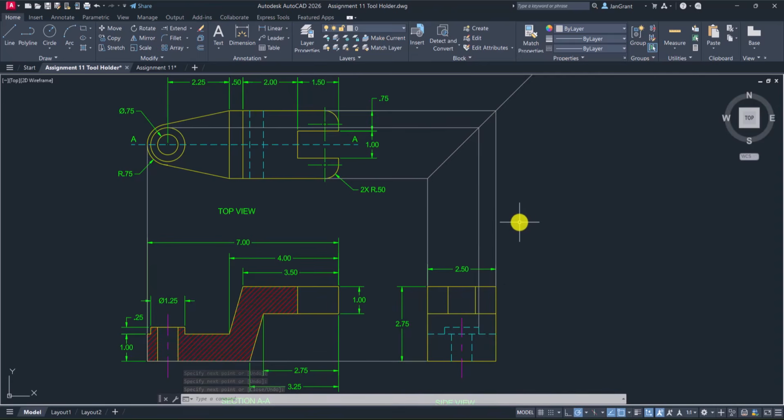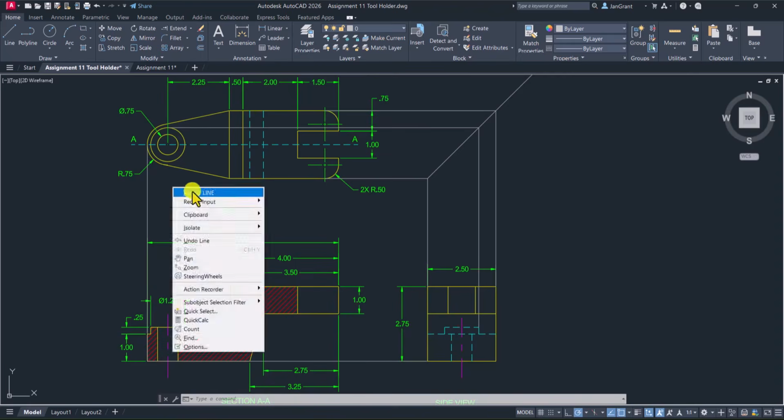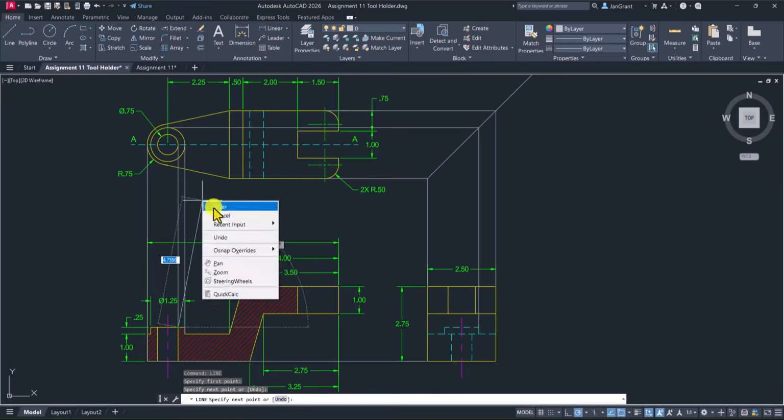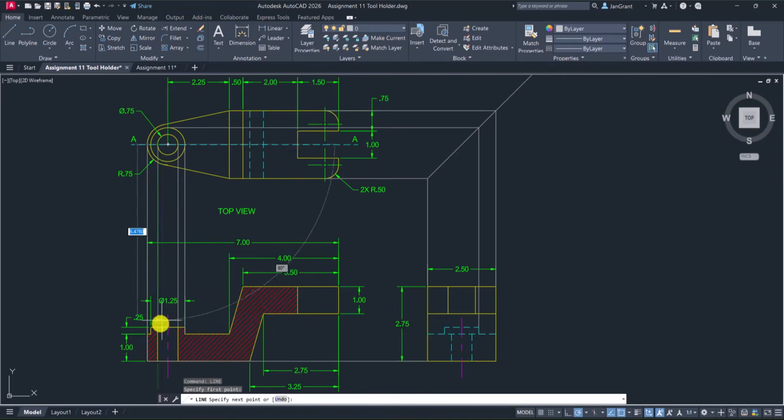Okay, and once you have it drawn and you work with these heights in creating the section, you'll be able to project all of these lines, like this one, down to find where this hole is. See how these projections come down to the front view or the section, which is what we're doing right now, to create this little part.